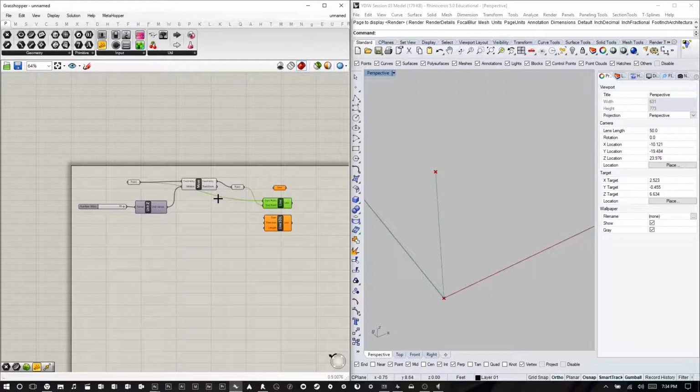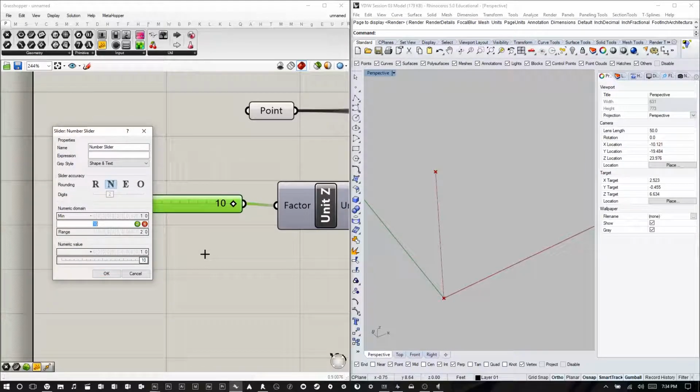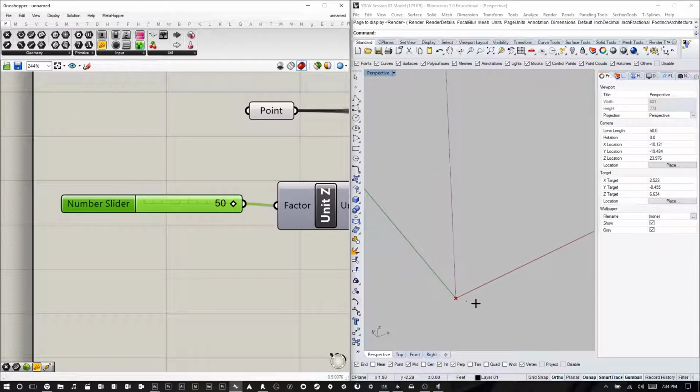We're now going to get into some more advanced stuff, and I'll explain each step of the way what I'm doing so it makes sense. So I'm going to create a spiral stair. And a spiral stair has some interesting parameters that you need to set in order for it to work right and for it to be parametric, which means if you give it a new input, it completely changes. I'm actually going to use this line as the base of my spiral stair. And I'm going to make it much higher, with a maximum of 50 feet. I'm going to move that point all the way to 50.